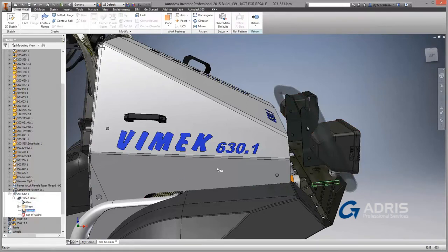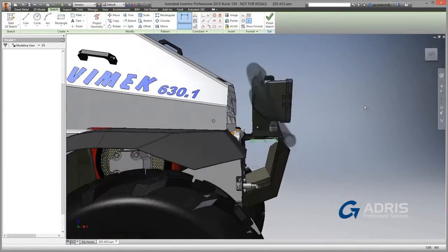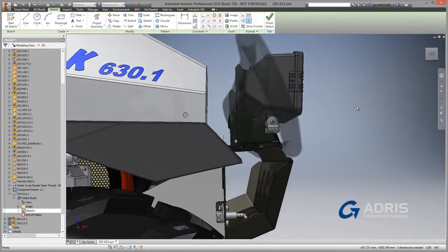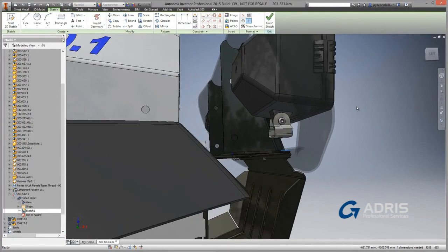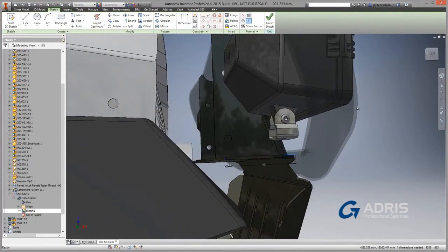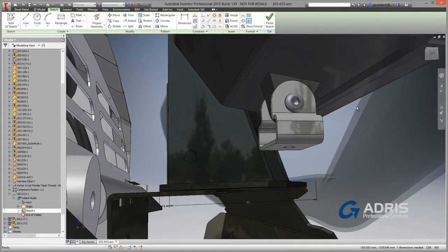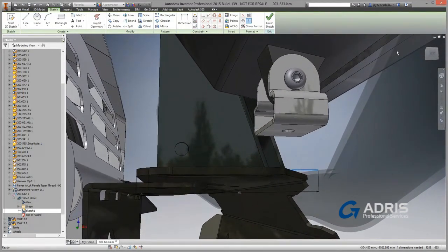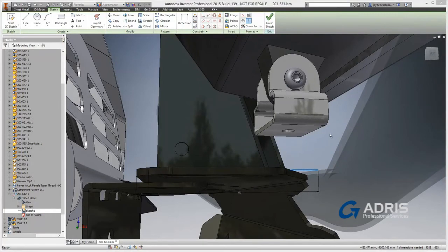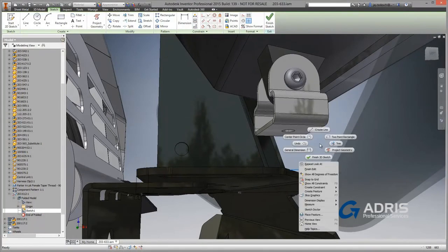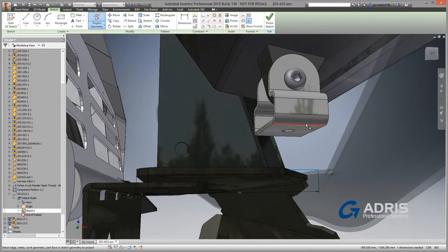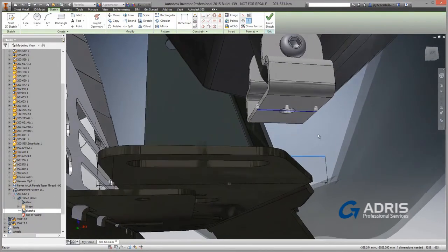I have a piece of reference geometry here, previously created. I don't want to be redundant here. I just want to make sure that we show you the constraint settings and the changes that have been made to the sketching constraint environment, because they're very, very powerful additions now. So we'll start by projecting some geometry. We'll pick this edge, and you'll note that immediately we can see the display of the constraint. So this is locked. It's projected geometry, so the geometry itself is locked.